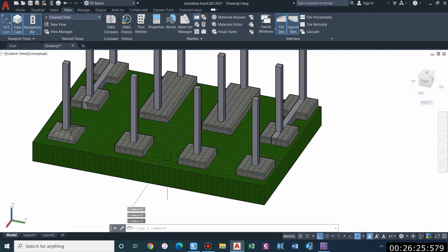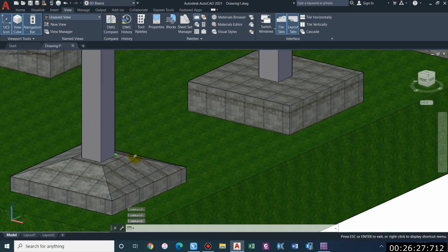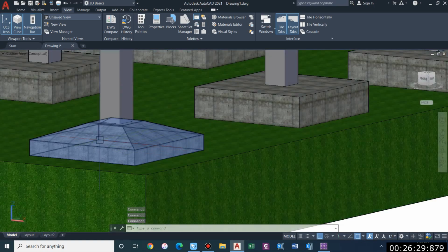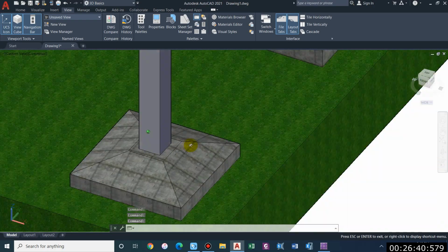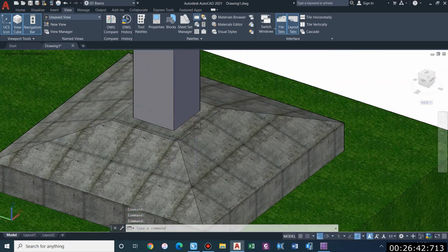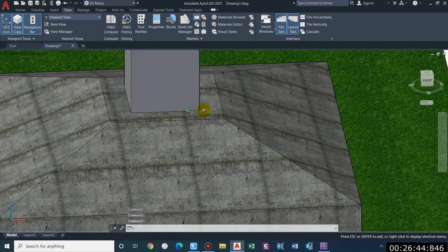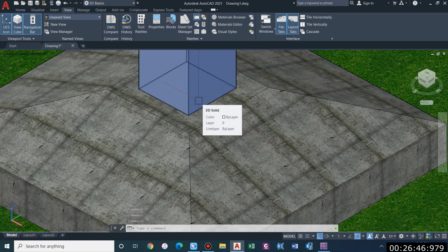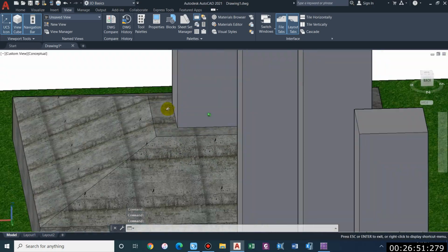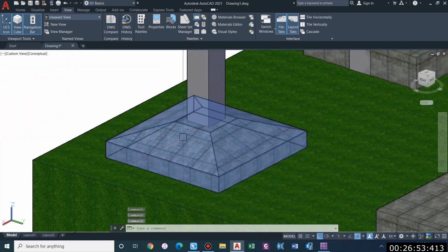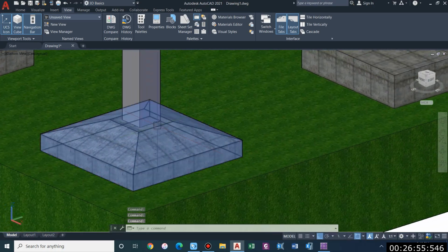But in some cases you might have seen a slope type footing as well, in this way. This is provided when there is no need of top reinforcement, that is, only bottom reinforcement is necessary. So we can select this type of footing and we can save the quantity of concrete as well. But make sure to give a certain projection like this, that is the offset on either side to support the formwork, and generally it should be at least 100 mm on either side. So this is how the isolated footing is constructed in the field.